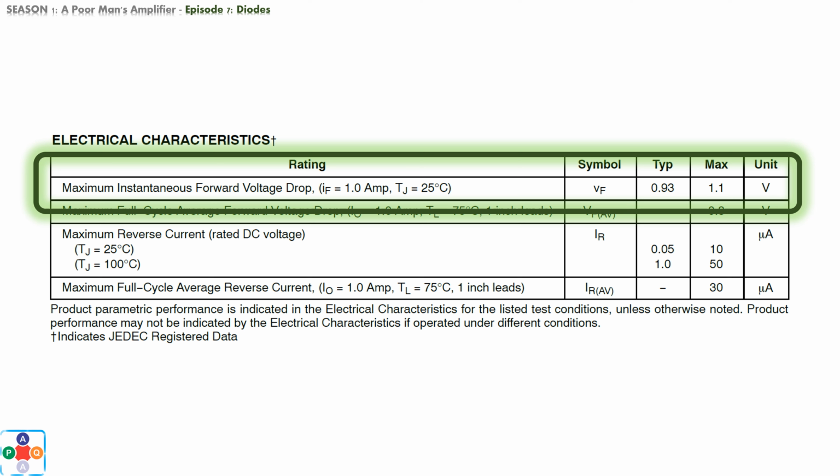Again, simplified, this says that ambient temperature in the laboratory was 25 degrees Celsius, and that all of the components, including the diode itself, were at room temperature at the time the test had been conducted. This parameter is marked TJ, which stands for junction temperature, where the term junction describes the contact points of the diode with the rest of the circuit.